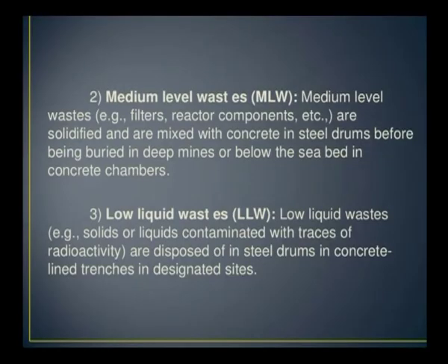Medium level wastes like filters, reactor components, etc. are solidified and mixed with concrete in steel drums before being buried in deep mines or below the seabed in concrete chambers. Low level wastes are solids or liquids contaminated with very small traces of radioactivity. They are disposed of in steel drums in concrete lined trenches in certain designated sites.